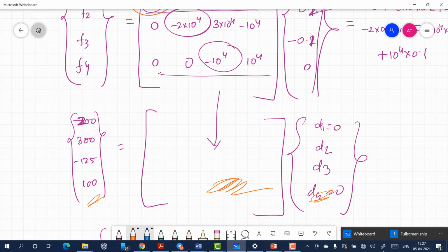Okay. The things are not so straightforward. So sometimes you have some values known here, sometimes you have some values known there, and you get a solution numerically from finite element analysis, and that's how you find out the force and displacement. From force and displacement, you calculate the strain. From strain, you calculate stress, and so on and so forth. So that's how we do it.